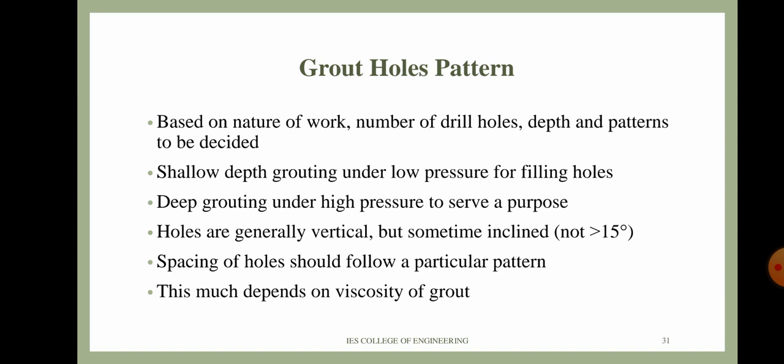Grouting may be of shallow depth with low pressure for filling holes. That is, shallow depth grouting is used for filling holes, while deep grouting under high pressure serves a particular purpose. The grout holes are generally vertical but can sometimes be inclined, but this inclination should not be greater than 15 degrees.